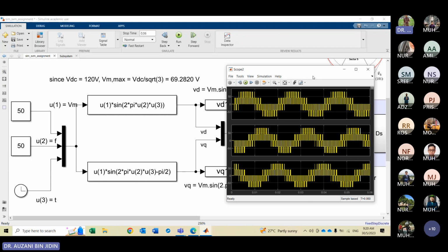It gives you a graphic application, that's why you place this part to make it faster. But the scope slows the calculation because it has to calculate the graph again to plot the graph. So better you close the scope and use the XY graph. Close.